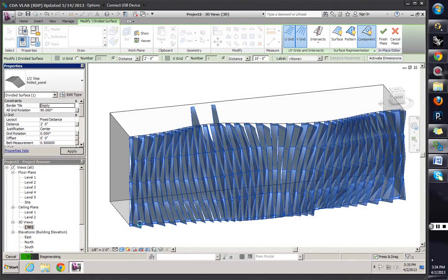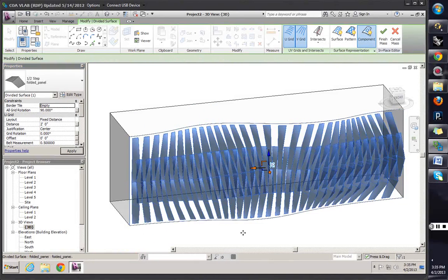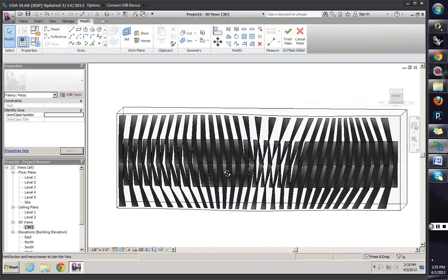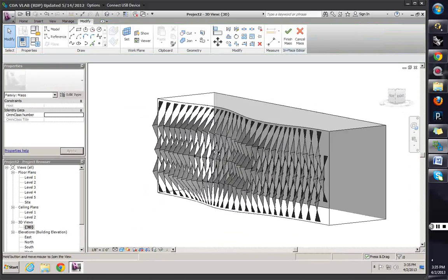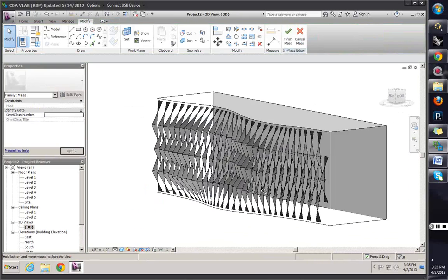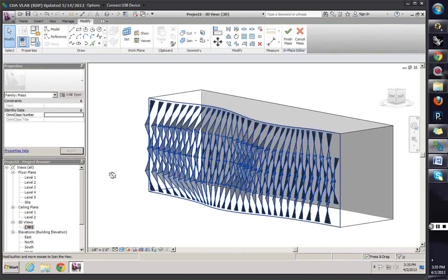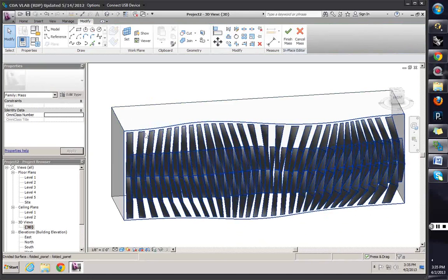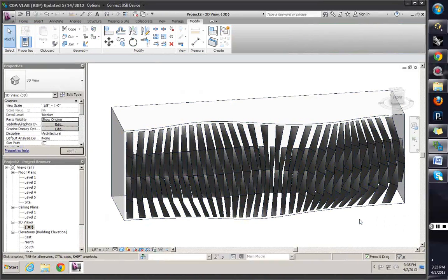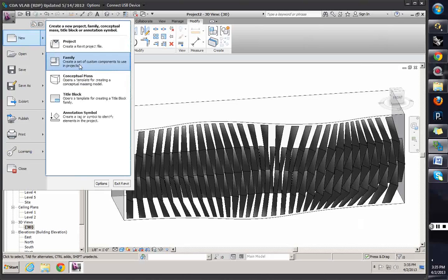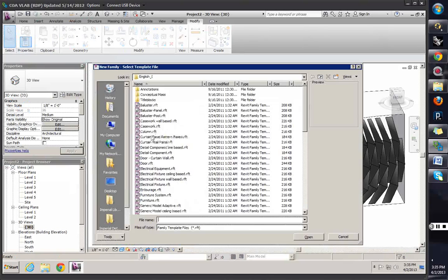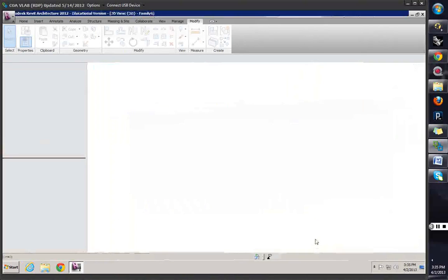And it's regenerating again. It will remove the half panels that we have at the bottom and at the top, and this is kind of what it's giving me now. And now we need to stitch them up. So what we need to do is create a new rectangle tile and create them in these empty tiles that we have. So I'll just finish this surface option for now, and then we need to create a new family, go to Revit, new family, and that's going to be curtain panel pattern based as well.